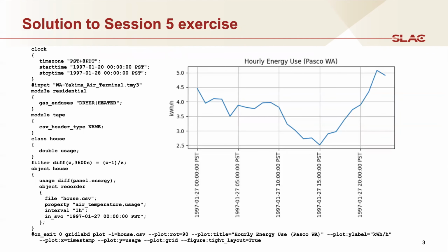In this case, what we've done is the first thing is we've set the clock. And notice that the clock starts about 1 week before the simulation itself is needed to start. So the data collection starts on the 27th, but the simulation starts a week earlier. This deals with the simulation transient that might occur as a result of setting up the simulation.